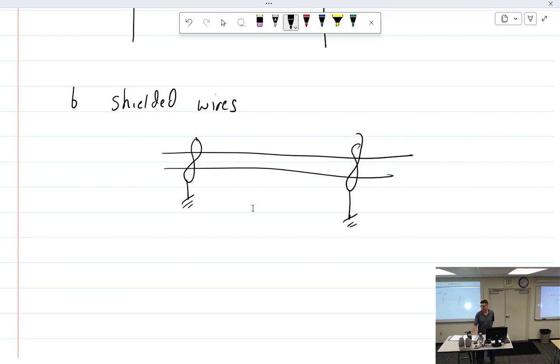Usually what you do in these, they have a special circuit with a ground lift. So if you get a ground loop, you can completely disconnect one side of the circuit. Okay. So yeah, I've been told now, don't ground both ends for sure. One end should be open and the other end is grounded. So I guess then it would just be ground whatever end is easier to ground. What do you think? So you want to ground one of the ends.